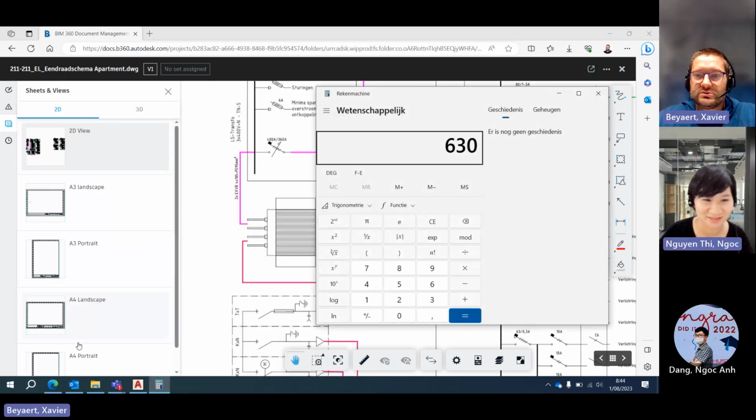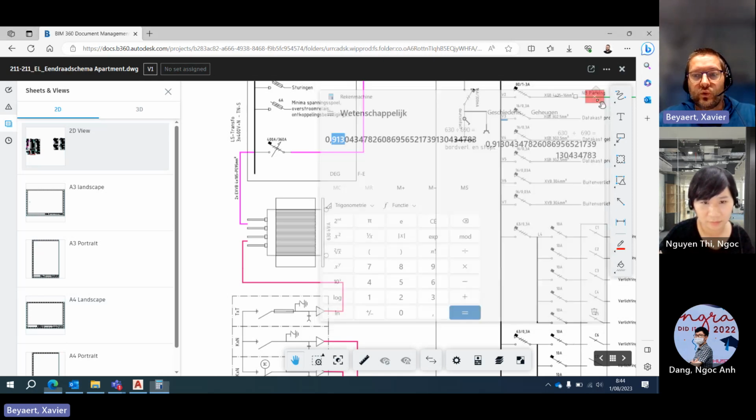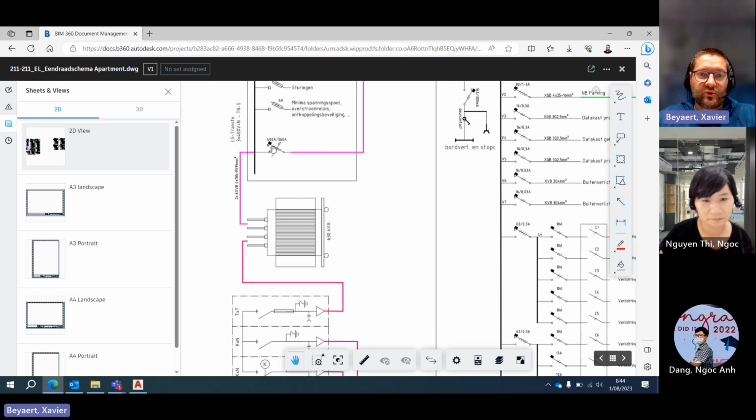That one I have not changed yet. No, no, no. So if you have 630 kVA, you can put 913 amps through it. So here we'll have a protection unit of 1000 amps that regulates it to 910 amps. So that's the way we calculate. We see what's the main circuit breaker. So you just look at the power of the transformer, and that will be this one.